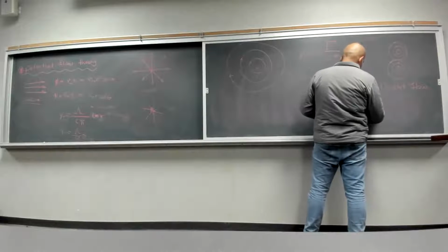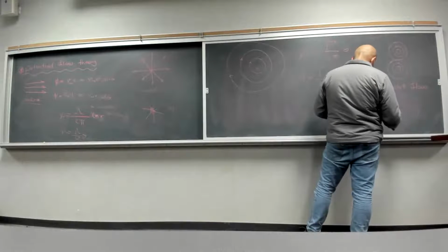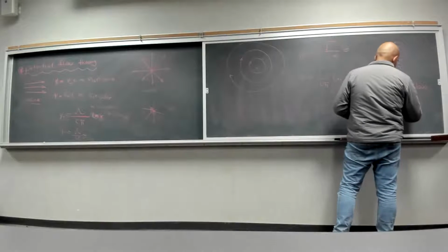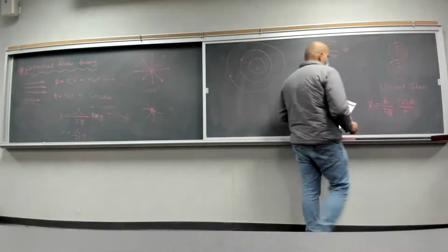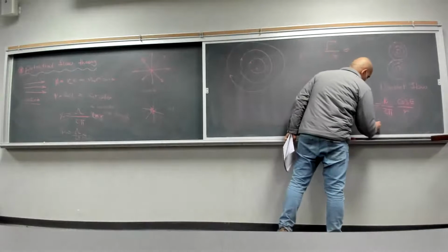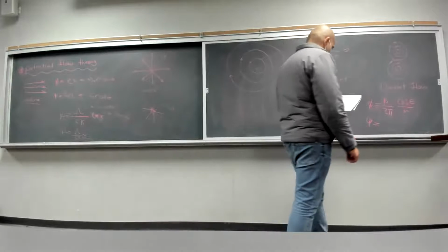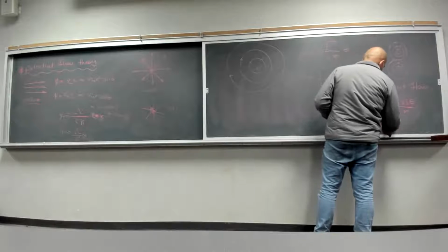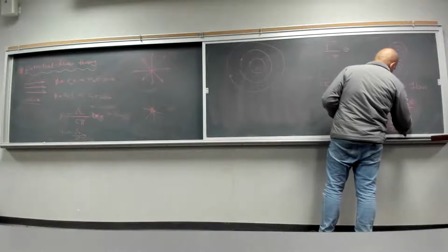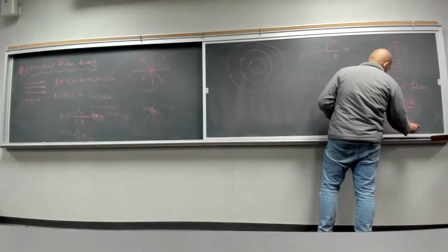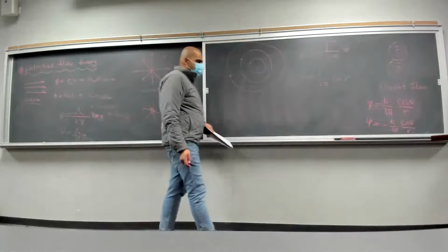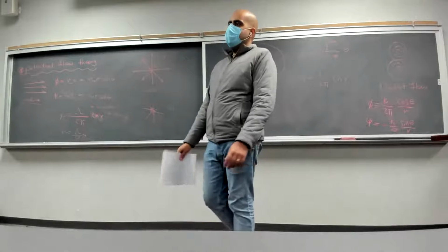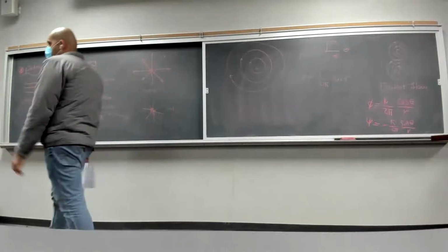Your phi is going to be equal to kappa divided by 2 pi cosine of theta divided by r. And your psi is going to be equal to negative kappa divided by 2 pi sine of theta divided by r. So based on these two formulations, you can see that we are going to have both VR and V theta for the doublet flow.